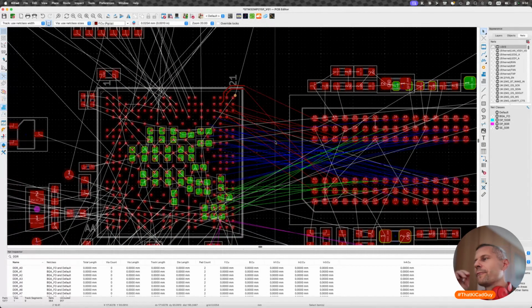To avoid future inevitable crossings, I think I should fan out on the top only the signals that won't cross, and then use the vias to fan out all the signals that will go to the bottom.